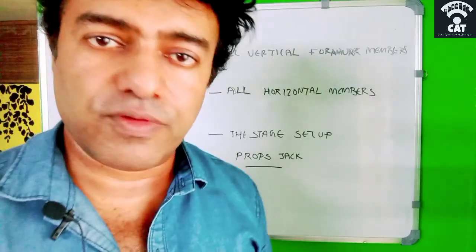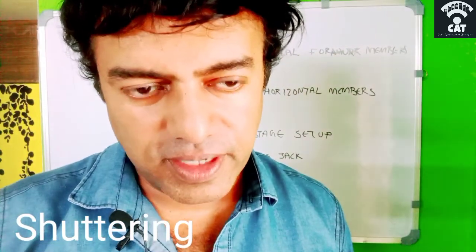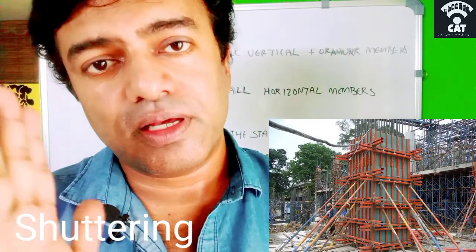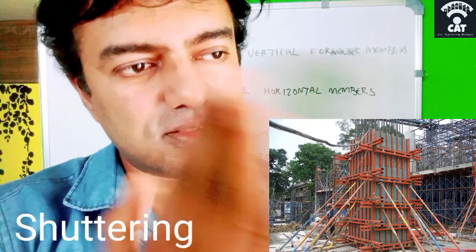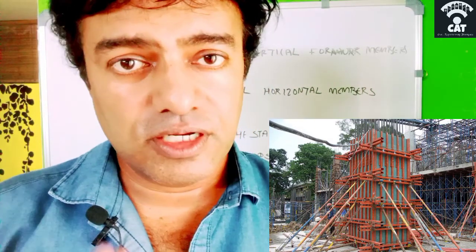And now we come to shuttering. If we take the example of a column, it's a vertical member, you know. So what goes to that vertical member will be the vertical plywood formwork on all four sides. That type of vertical member formwork is called shuttering.